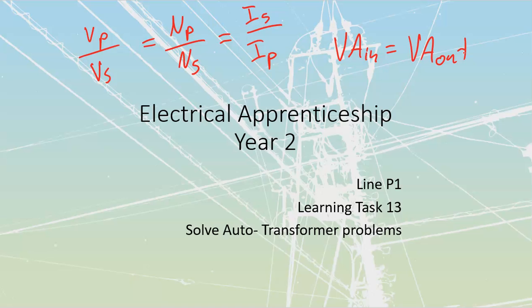It's sometimes easier to figure out what we have at the load, figure out what we have at the source, and then work back in from either side before we try to analyze any of our currents. That way we know where we should be ending up, and if what we have coming into the transformer doesn't line up with what we have going out of the transformer, we know that there's an error inherently, and we just have to go back through and sort out where that is.